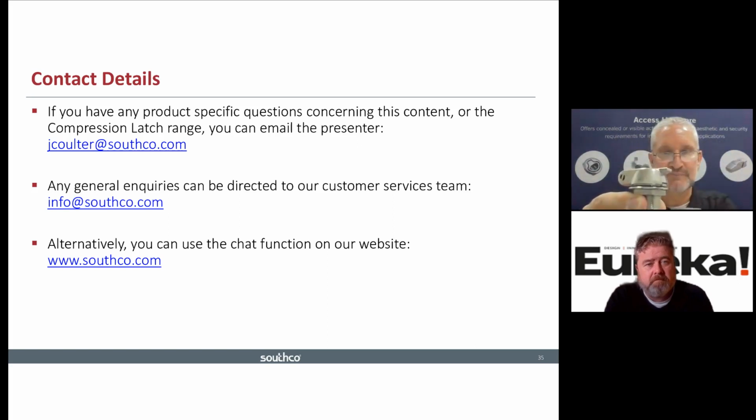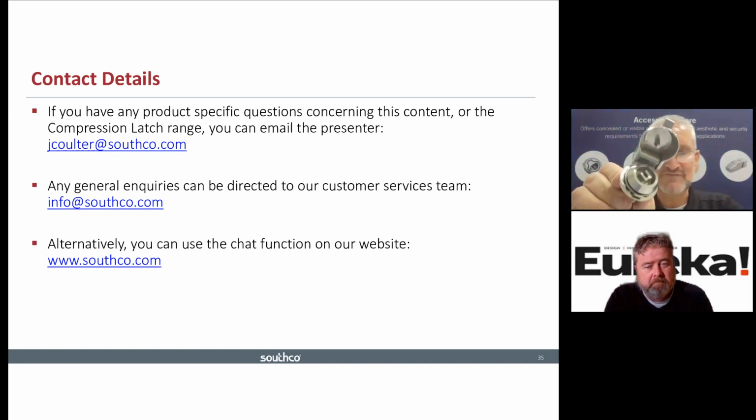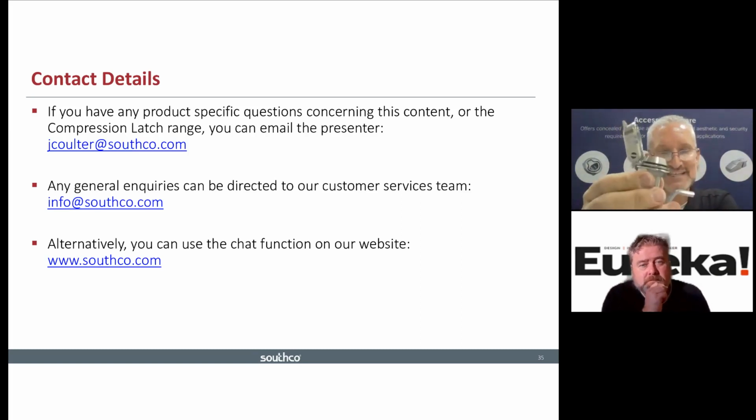There's no middle ground. So you can see that when the latch is closed, this cover, which has a fin inside, can nestle into the latch head and be completely closed. But if I were to open that latch and choose a common key to rotate that latch slightly open, which I'm going to do now, you'll see that the driver notch is no longer in alignment with the fin, and I can't close that. It just pops open bistably, which means with this accessory, a simple add-on feature, I can see from a distance whether or not that latch is secure because the cover stands up proud.